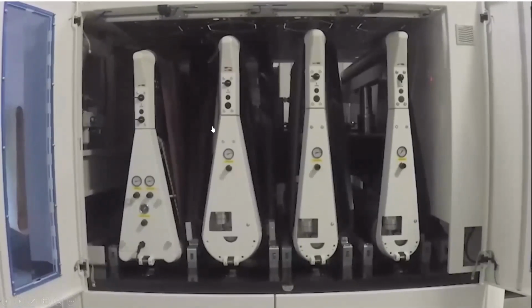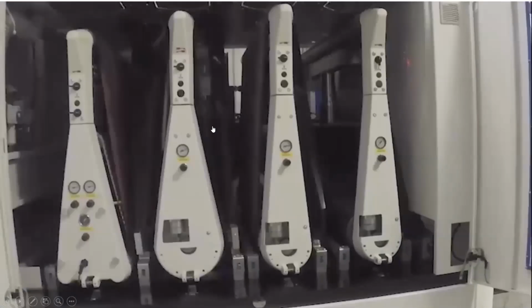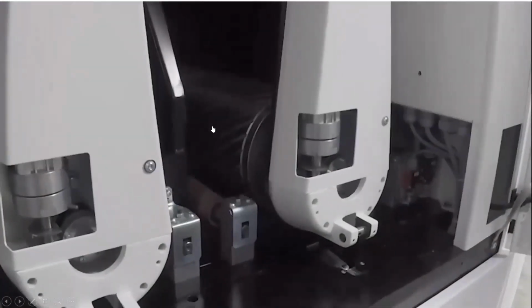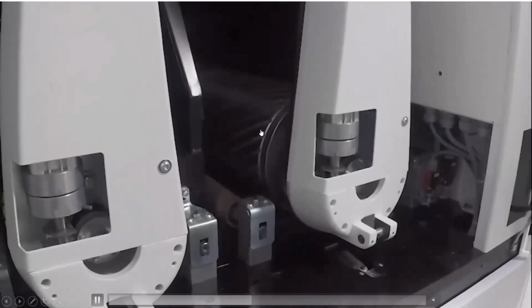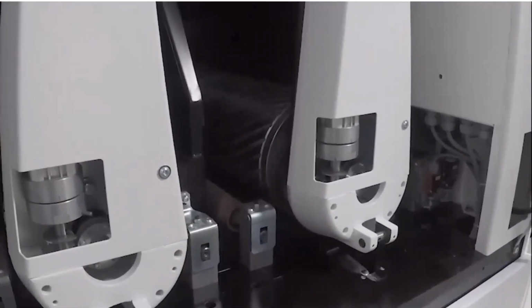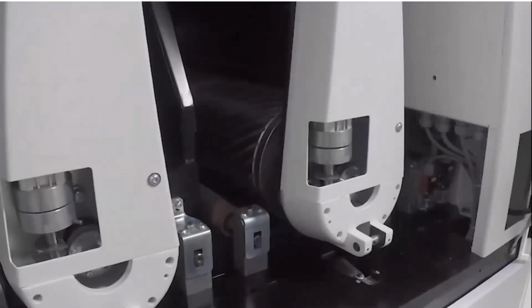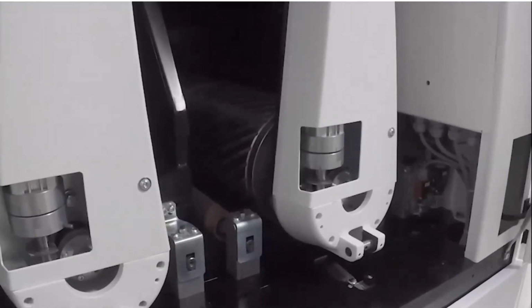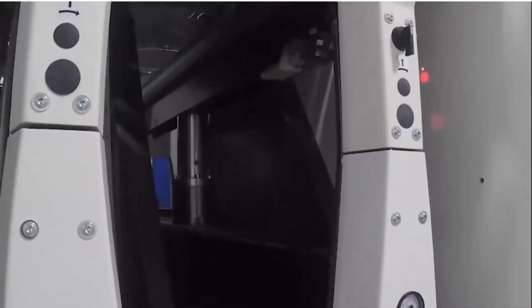Our first head is a steel drum. And as you can see in this picture, there's no belt on this. It's a helical steel drum. The reason it's a helical steel drum is because with steel, it's much more aggressive. It gives me a much more accurate calibration. The helical portion inside the drum helps the dust evacuate, and it also helps cool that head. This is a pneumatic cylinder that tensions the belt inside of the machine.